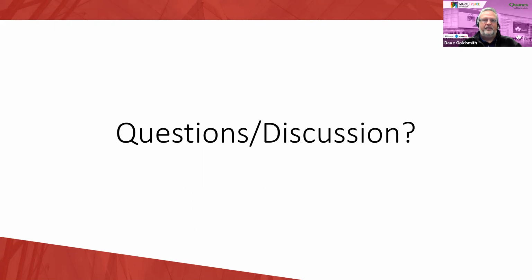Well, I think the simple answer to that question, I use the 1 in 50 hourly wind pressure. The code doesn't require buildings to withstand natural disasters. Otherwise, all of our buildings would have to be designed to withstand a tornado. That would make your buildings a little bit cost ineffective. So it's reasonable conditions. And it's worth pointing out that the specified wind loads are quite conservative, because they're basically assuming a worst case scenario with the gust factors, internal and external gust factors and pressure coefficients.